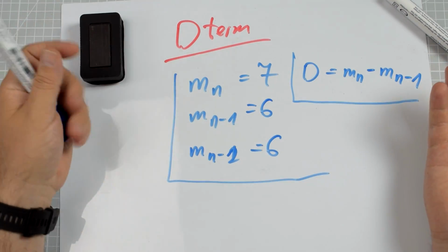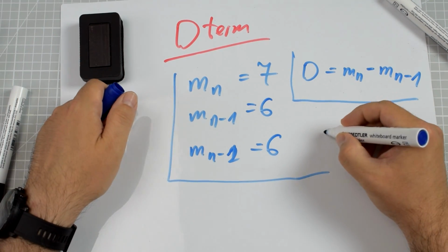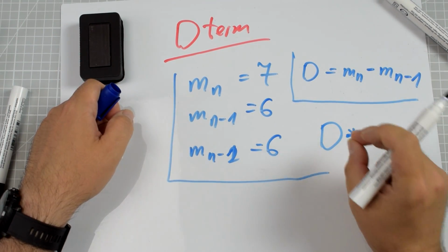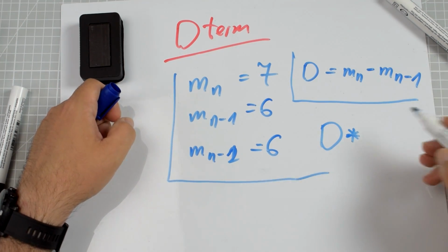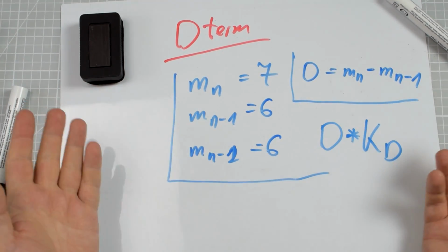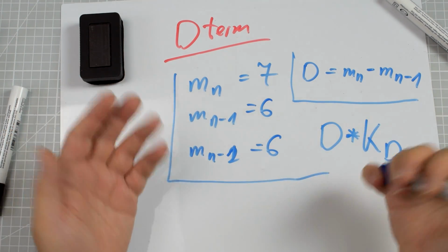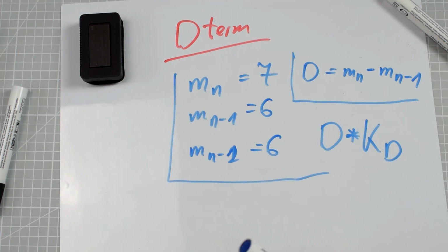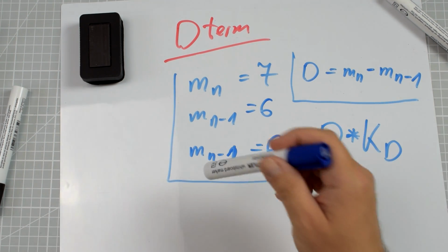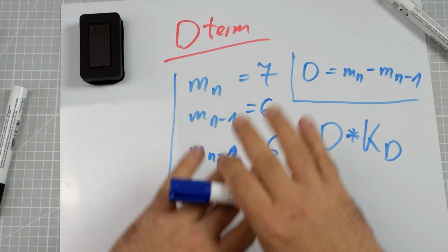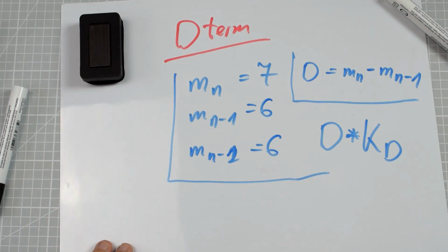And the D term is the derivative, the value of the acceleration in a given moment, times Kd, where Kd is the gain, just a number used to multiply the value of the derivative to compute the value of the D term that will be added to the P term, the I term, the FF term and all the other terms, and then introduced to the motor.